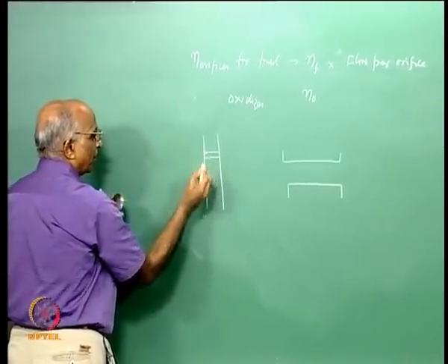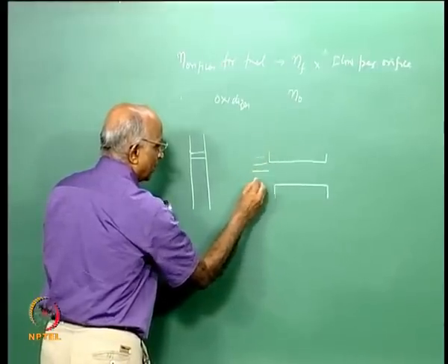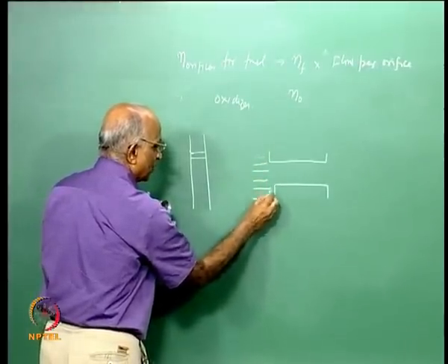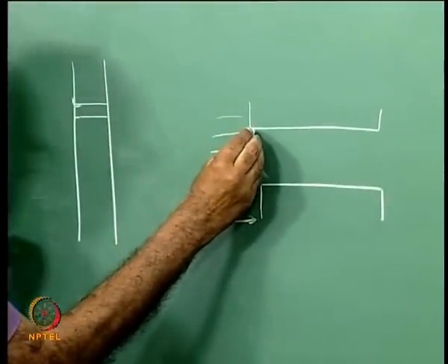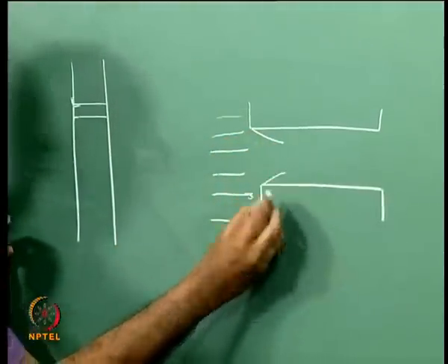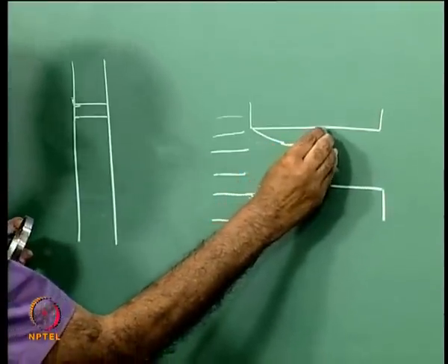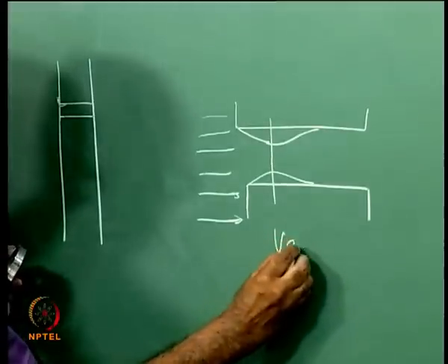the edge is very sharp. That means the edge through which the liquid enters from the manifold like this, it has high pressure here, almost 0 velocity, and when it enters it contracts to a minimum and then reattaches over here. This we call the vena contracta, right.